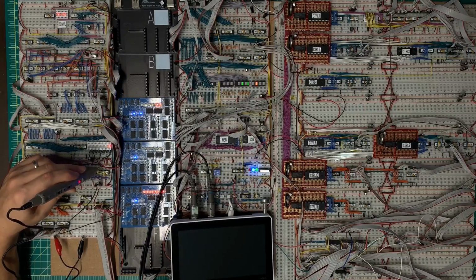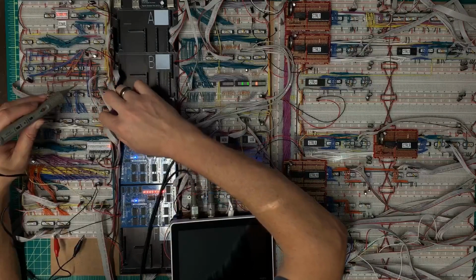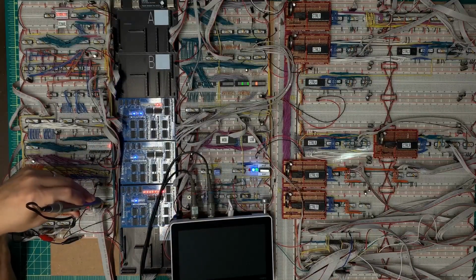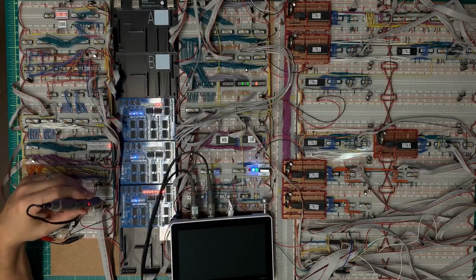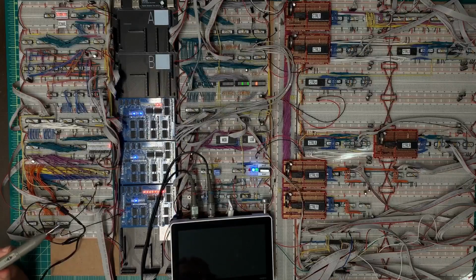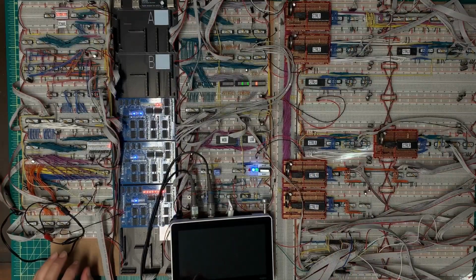I need to trace my carry select backwards. Carry select is, they're both high. These are coming off of here, high and high. So my carry select is high for a no op instruction. Okay, that leads me back to the programming of these things, these EPROMs. So which one is suspect?